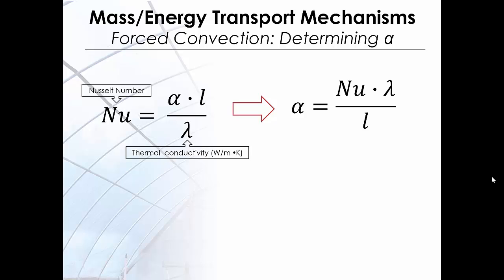In the Nusselt number, lambda indicates the thermal conductivity, and L represents the characteristic length, or the characteristic dimension of the surface. Selection of the characteristic length should be in the direction of growth or thickness of the boundary layer. For instance, some examples of characteristic lengths are the outer diameter of a cylinder in external cross flow perpendicular to the cylinder axis, the length of a vertical plate undergoing natural convection, or the diameter of a sphere.